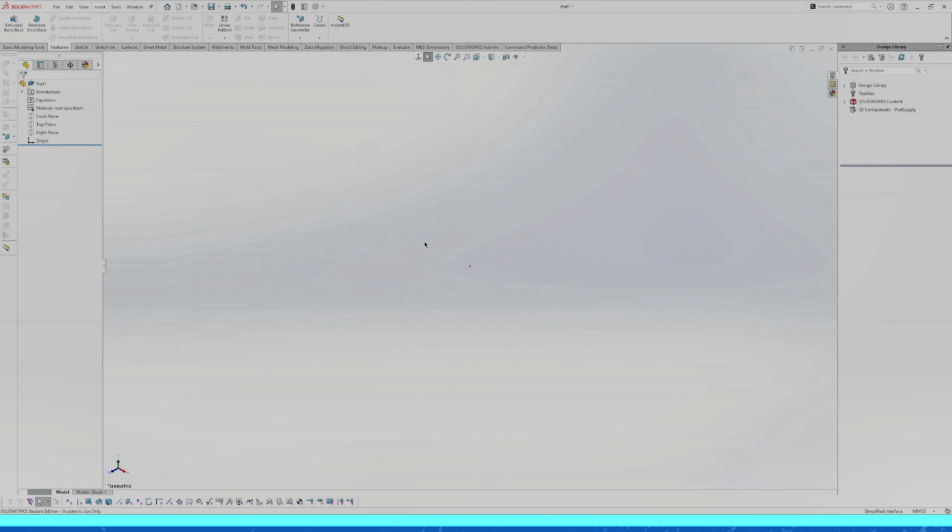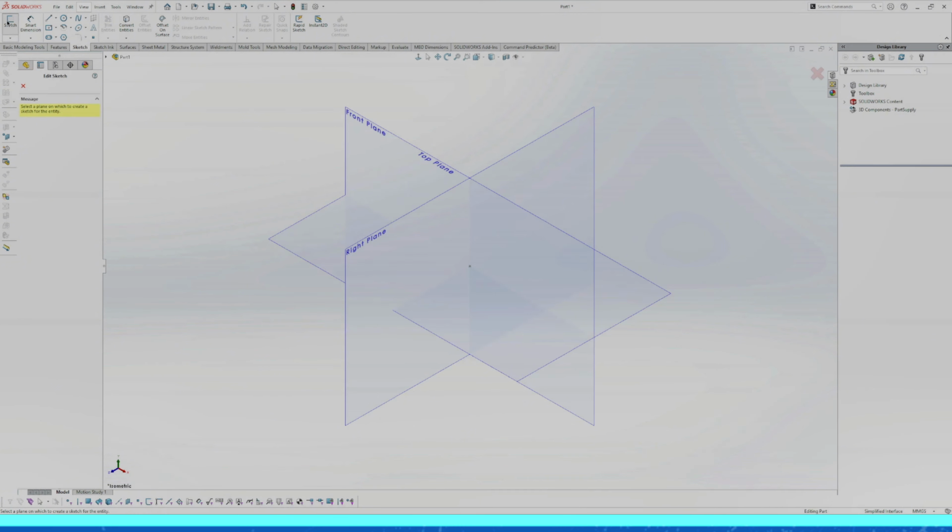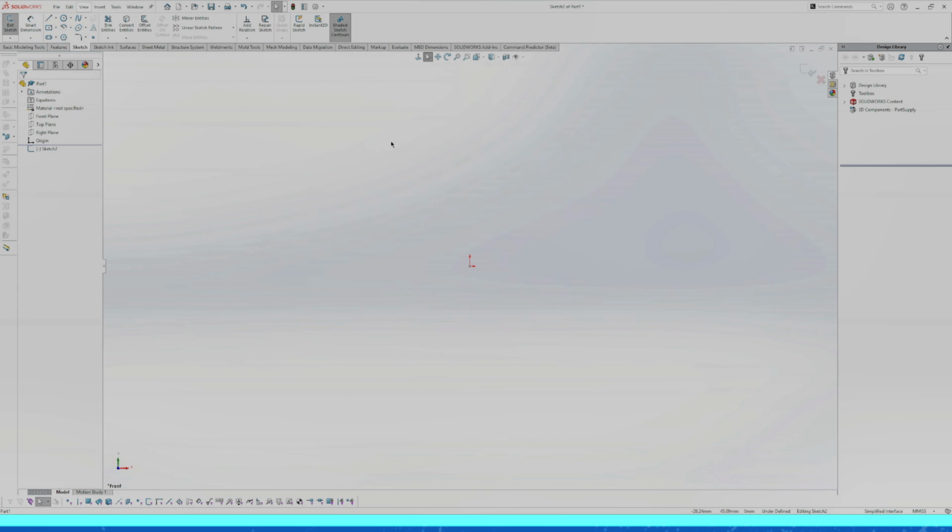All right. And then the basis of how sketches work in 3D modeling and CAD is we're going to start with a 2D object and then pull it into 3D. So we're going to go ahead to our Sketch tab, click on the Sketch icon, and it shows us three planes, the top plane, right plane, and front. I'm going to choose the front plane, and this gives us our origin. We always want to make sure that our object is on our origin, just so that it's easy to refer back to. It is our center point of the entire model.